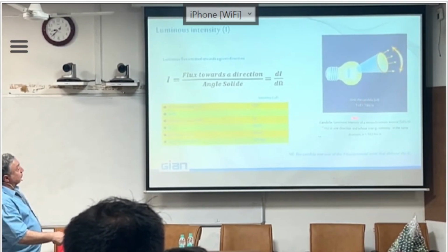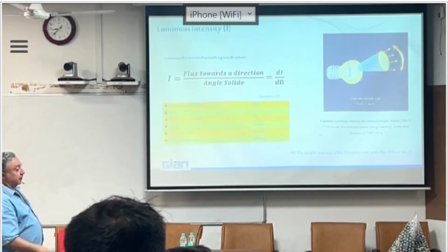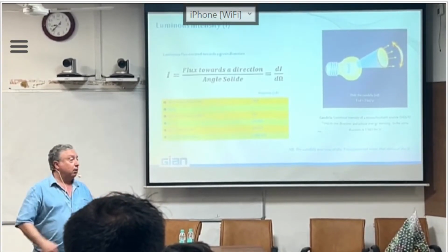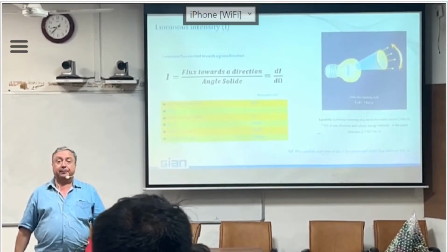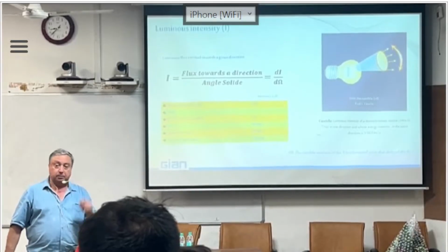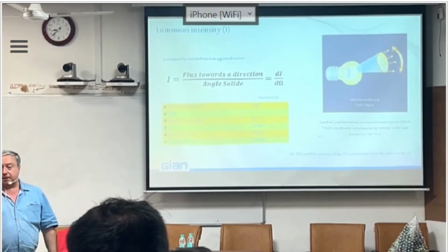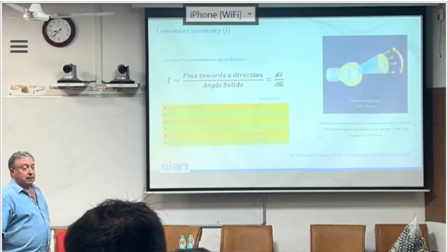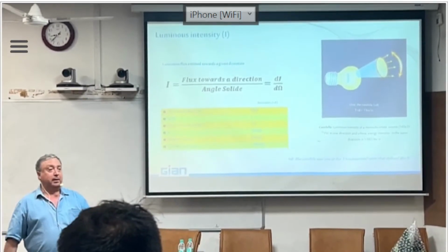And you can see here we measure in candela a light emitting diode, a red one, that just shows you that a device is switched on or off. It is 0.05 candelas, very small. A candle, by definition, is one candela, because it was the first standard of candela. We'll speak about that. A 100 watt incandescent lamp is 150 candles, 150 candelas.